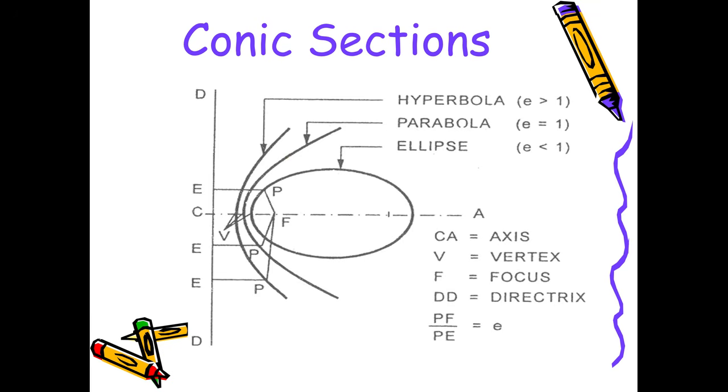Now observe the geometric construction concept. Every conic is defined using axis, vertex, focus, directrix. The ratio of distance from focus to distance from directrix remains constant. That constant ratio is eccentricity. This focus-directrix principle is the foundation for engineering constructions.